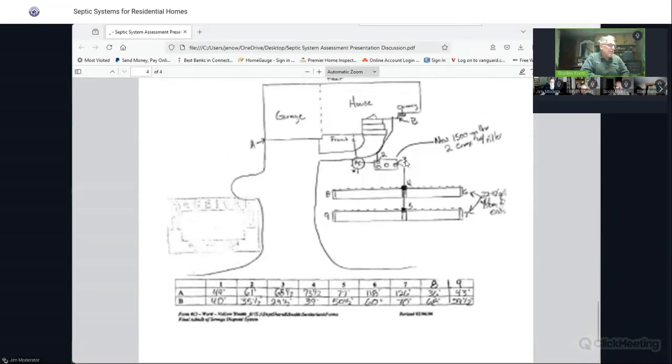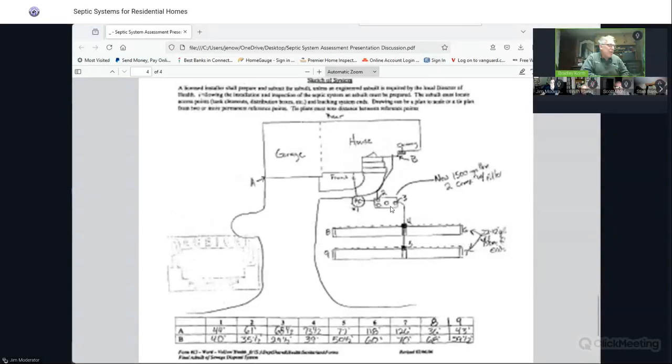And what was happening is all the stuff you see. Go just lay on that page. You see where it says pump chamber, PC, before the septic tank. The pump chamber is supposed to have enough storage volume for at least a day's worth of effluent in case the pumps fail. Remember I talked about earlier that this had a lower level basement. That pump chamber is really designed just for that lower level basement, with a reduced volume, and the main volume was supposed to come out of that line that wasn't there.